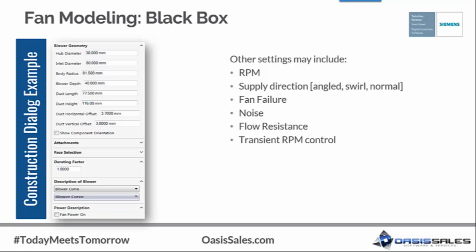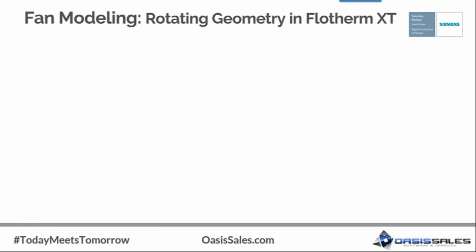In FloTHERM XT, there is an additional option when modeling fans. FloTHERM XT can simulate the rotating geometry. There are two options available for rotating geometry, each with strengths and requirements that we will discuss. The first option is rotating reference frame.